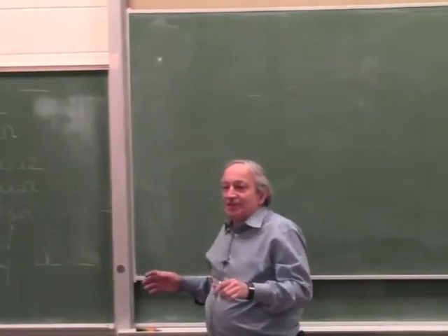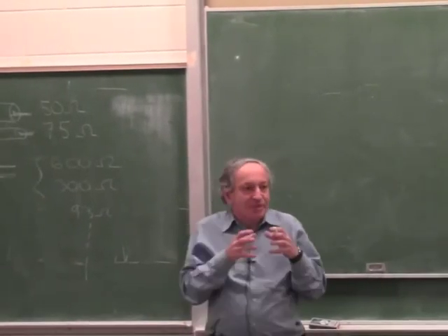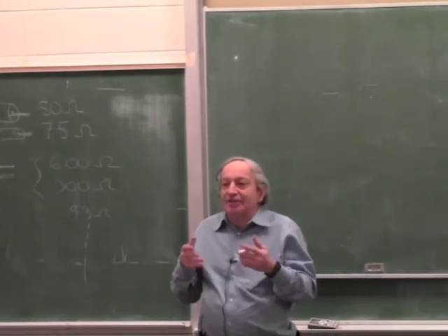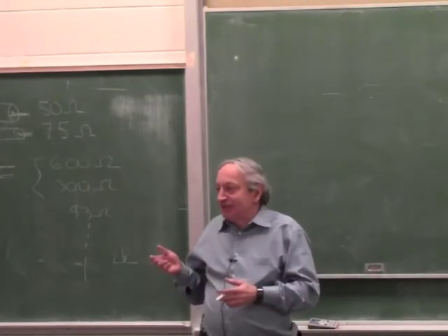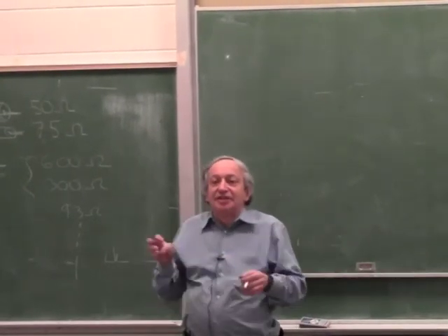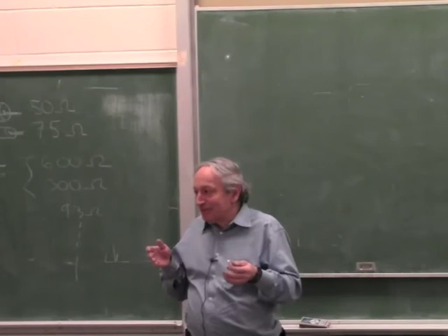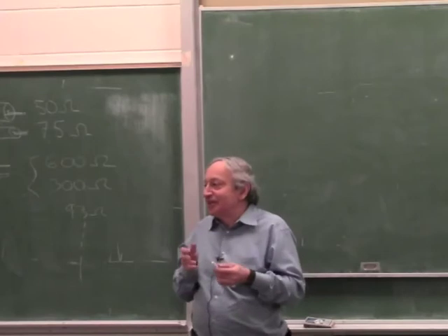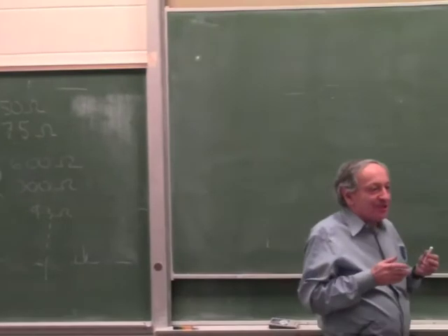That's very important to understand, and reminding you of the demo which I gave you last week, I had a sealed metal box, all metal all around, and it had a coil and an LED inside, and the LED was lighting up when I put it in a 60 Hertz AC electromagnetic field. I had an electromagnet plugged into the 60 Hertz. When I held it next to this box, the LED lit up. And to light up an LED, you need a lot of volts, like 3 volts, in this case a blue LED. So this little box, although it was all metal, there was no problem generating 3 volts inside. So that's very worrying, which means this whole concept of shielding has to be treated with great care.